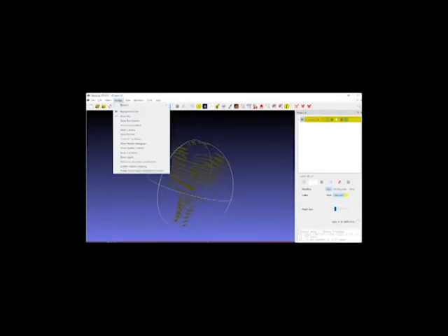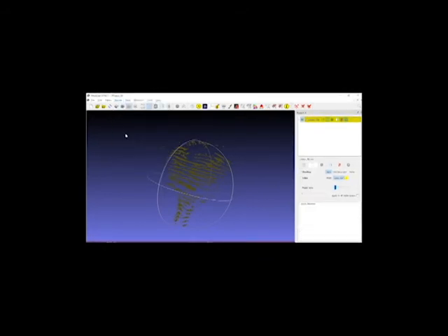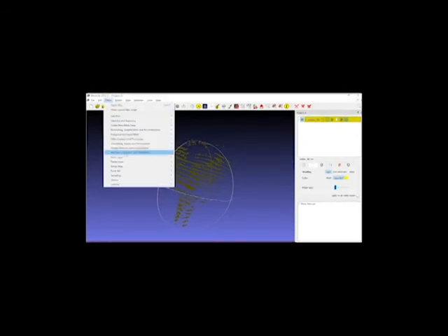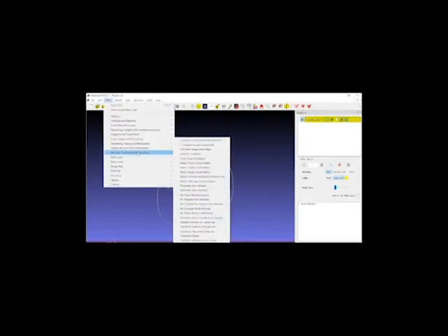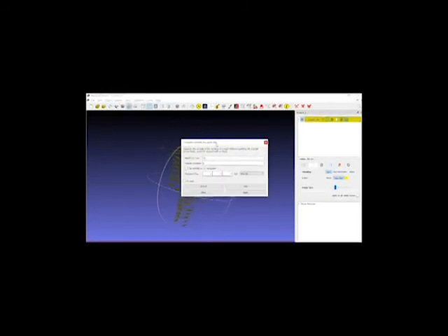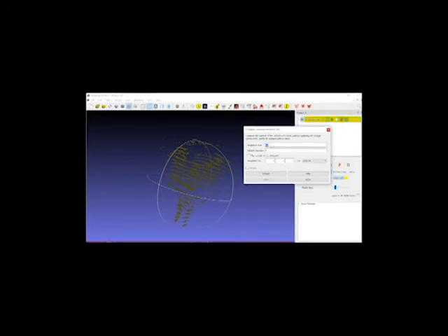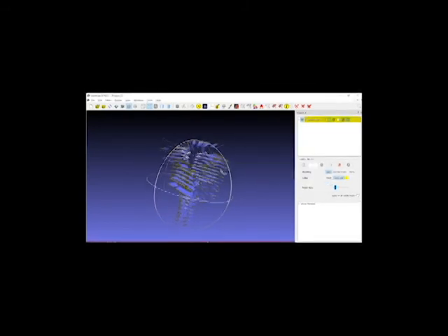We first go to Render, Show Normal, and then we want to create the normal, which basically says where the planes are. So we go to Filter, Normals, Curvatures, and Orientation, Compute Normals for Point Set. Now, I can't tell you how I found these values, but I found out that these values work if I use 1750 for neighbor numbers, turn on Flip Normal with respect to orientation, and click Trackball Center, and hit Apply. You see I've created all the normals.